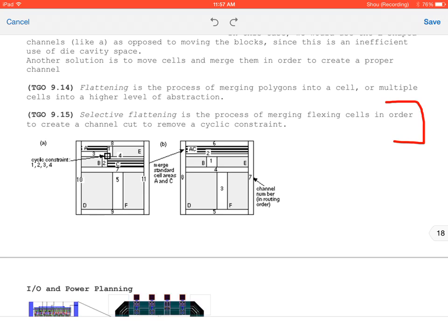So again, this is all kind of a higher level. Floor planning is its own field, right? And floor planning isn't just in CMOS. Floor planning is, as I alluded to earlier, a huge aspect of FPGA design, of advanced digital systems, all of that. So basically being able to lay it out in a way that consumes less power and being able to meet your performance constraints all ties into floor planning.